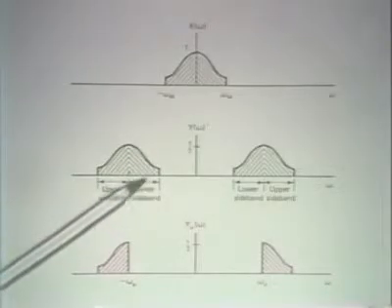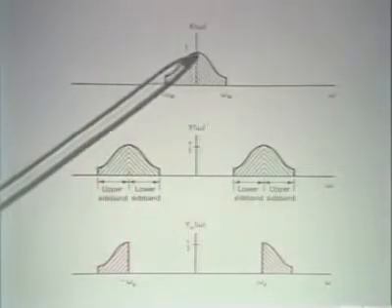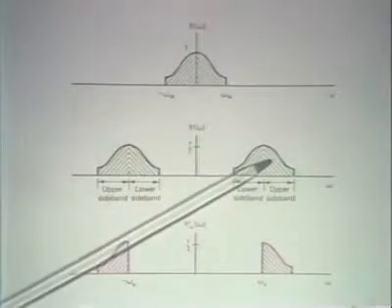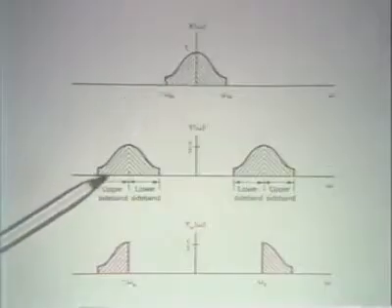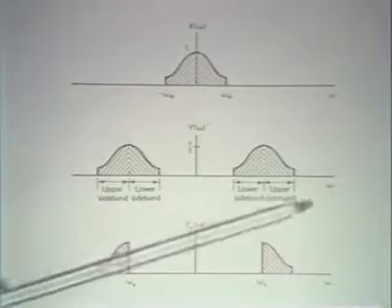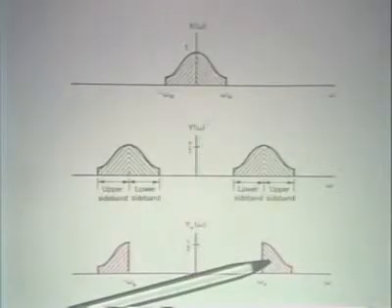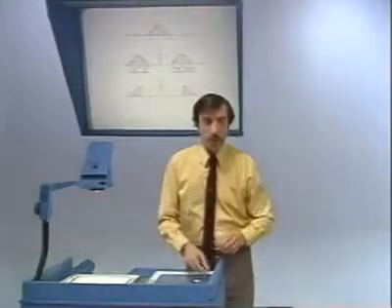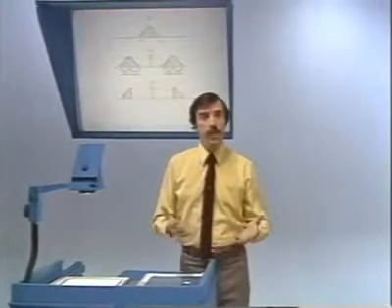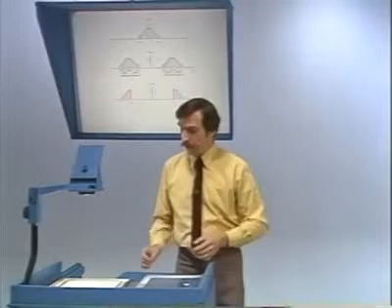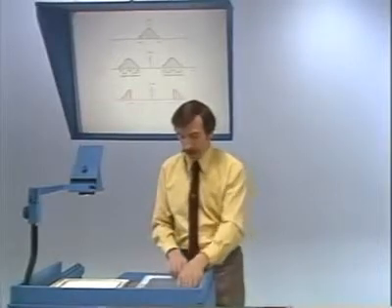In effect, what we've done is taken just the positive frequencies here, shifted them there, the negative frequencies here, and shifted them here, and the resulting spectrum is what I indicate below. Well, this, in fact, is what is often done, and it's referred to as single sideband. What we've done is we've kept the upper sideband in this particular case.